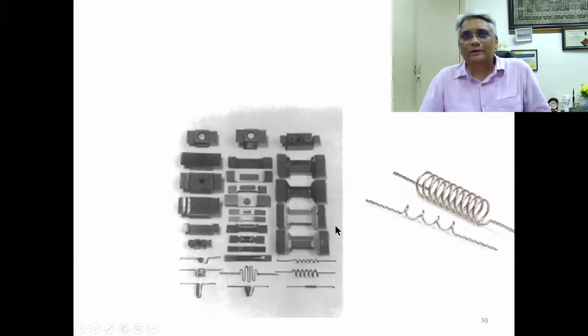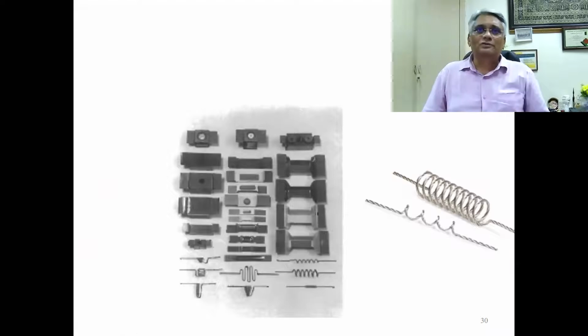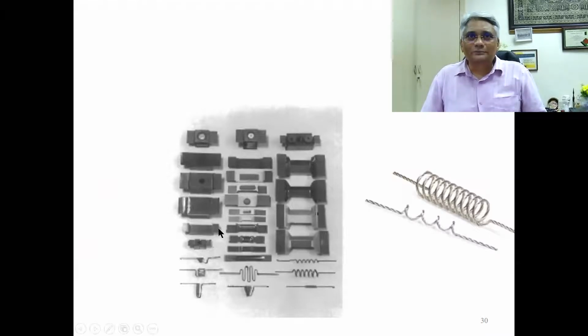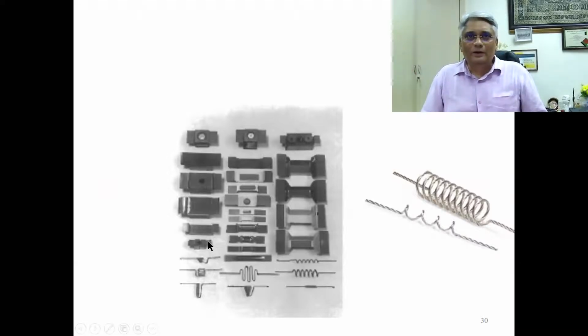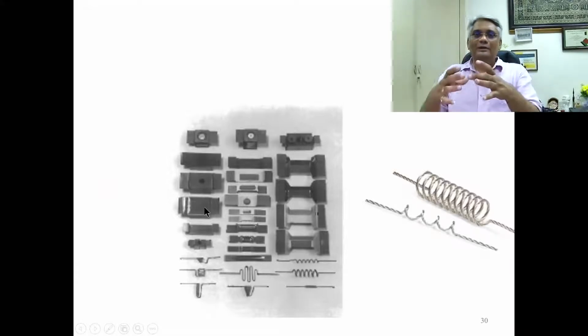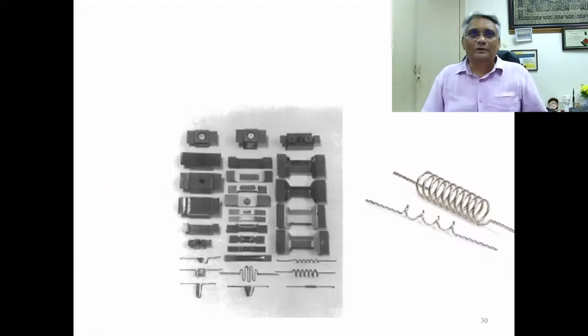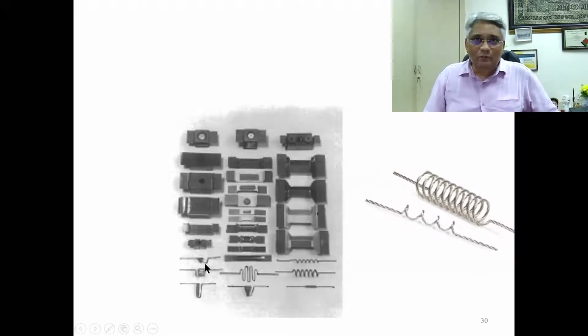It all depends on the requirement. I want a small amount of charge to be heated, so I make a small boat like that. This is from a tungsten sheet. I can easily cut it and fold it in such a way that I make it into any specific form I want. Bigger boats, because I'm melting 15 grams of the alloy, and you see the bigger ones. And you also have these wire heaters, no? Very famous wire heaters. Why do I want a wire heater or a heater wound in the form of a conical basket? You see that?